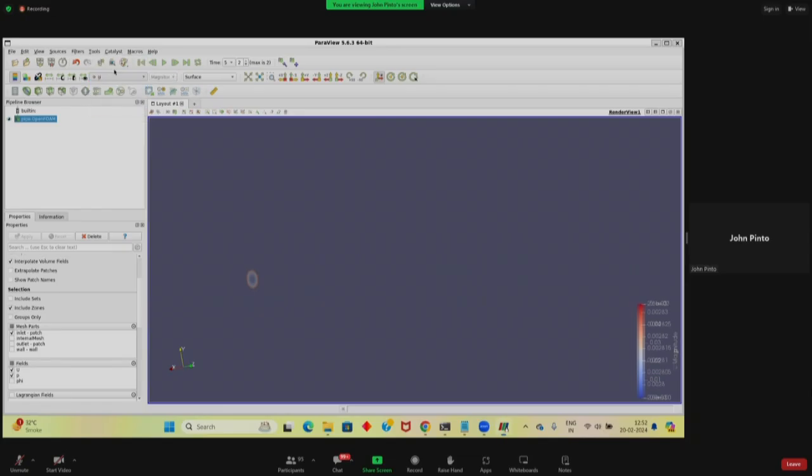Okay, this coloring is pressure. The value is very low. It is not 0. The value is very low. The color scheme is such that I am feeling that the value is 0. Yeah. So what you can do is you can select P over here, pressure, and you get all the pressure values.